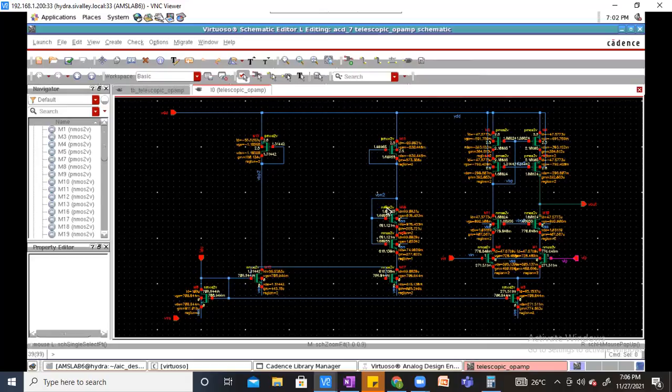Okay. We'll do other analysis on the same Opamp. It will be fixed. It's very easy. Just try to tweak this branch, this MOSFET and this MOSFET. And it's not necessary you should fix it. So region 1 is also fine for me, but it's supposed to be region 2. Any questions, guys?